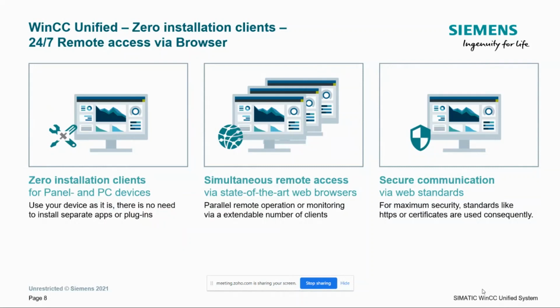But what it allows you to do is to put the security between the PLC and the HMI, because the communication between the HMI and the PLC is where the man in the middle can really hit it the hardest, because it's always communicating back and forth. So this software gives you the capability to say who can communicate between the PLC and the software, etc. And you can put different levels of it. So it's just an added secure software that just came out.